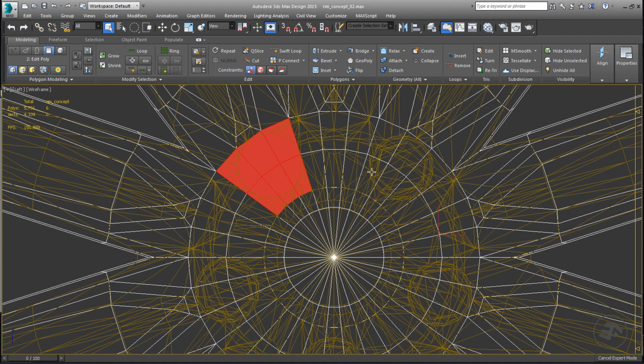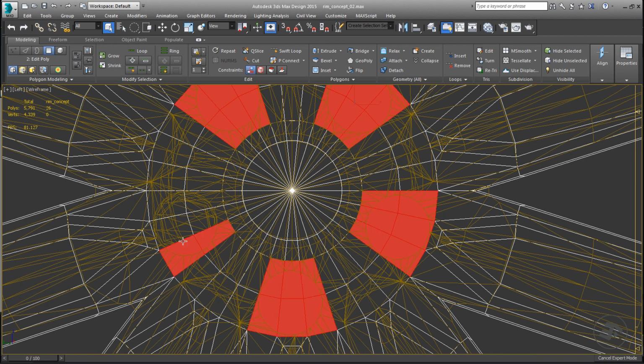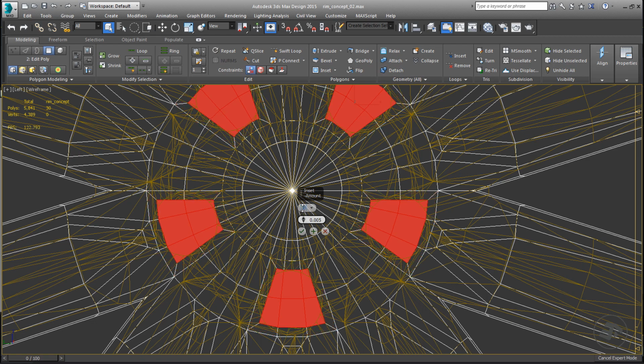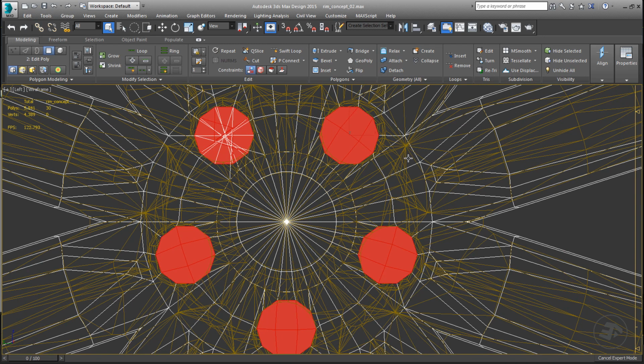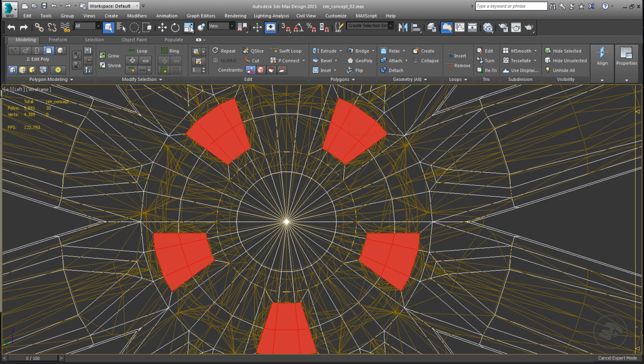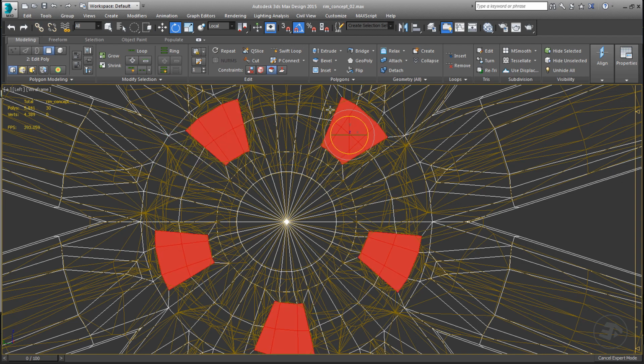Select the polygons in the same formation as shown. Use Insert by Group to insert a loop at 6 mm for each group of the selection. Use the Regularize script to turn each group into a circle. The script works on editable poly geometry. However, on Edit Poly, if I keep pushing my luck, unfortunately, it will break. Here is some frustration while using the Regularize script.